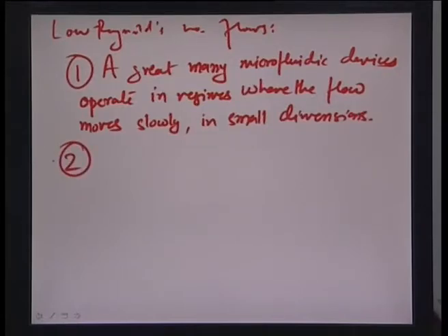Say for instance you are talking about a very thin piece of channel or a very thin size of the micro channel which is defined by photolithography. So there the channel thickness is defined by the film thickness, and the film thickness could be anywhere between, let us say, 20 microns all the way to about 100 microns or so. Now 100 microns is effectively the diameter of a human hair. So you can consider what is the effective volume through which this flow would actually flow. And it is very obvious to assume that the flow rates typically would be a few microliters per minute.